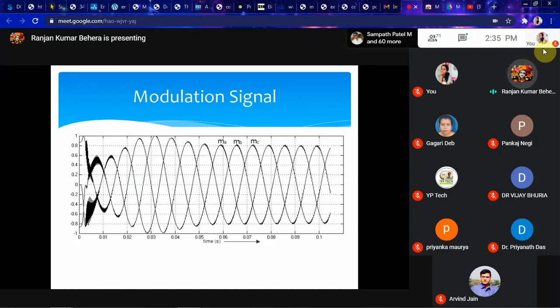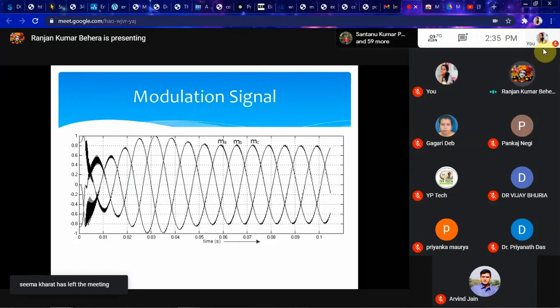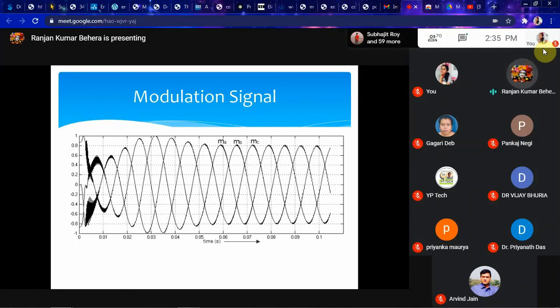There may be high frequency noise due to the switching of the converter, which is propagated to your control circuit. Second, it may be due to line stray inductances, where there may be a resonant effect that may also create more electromagnetic interference.